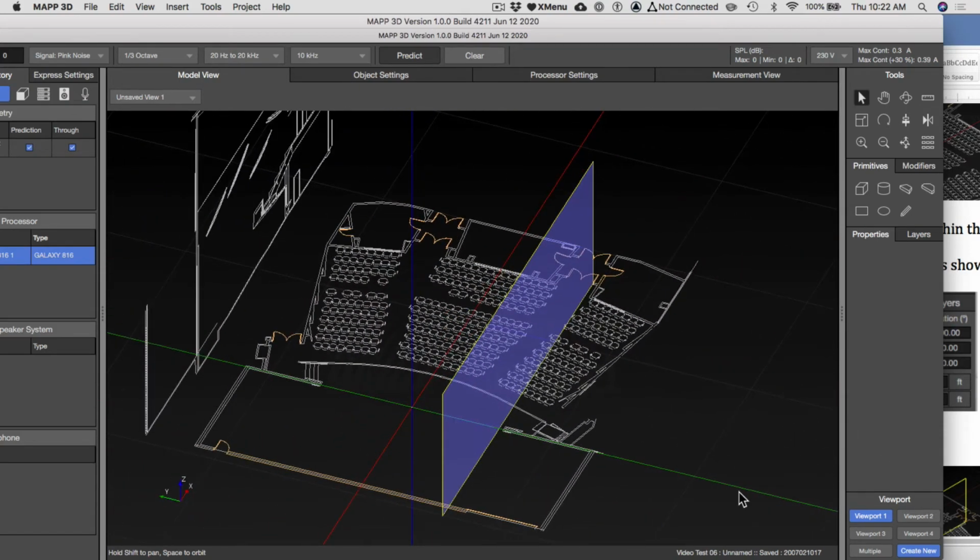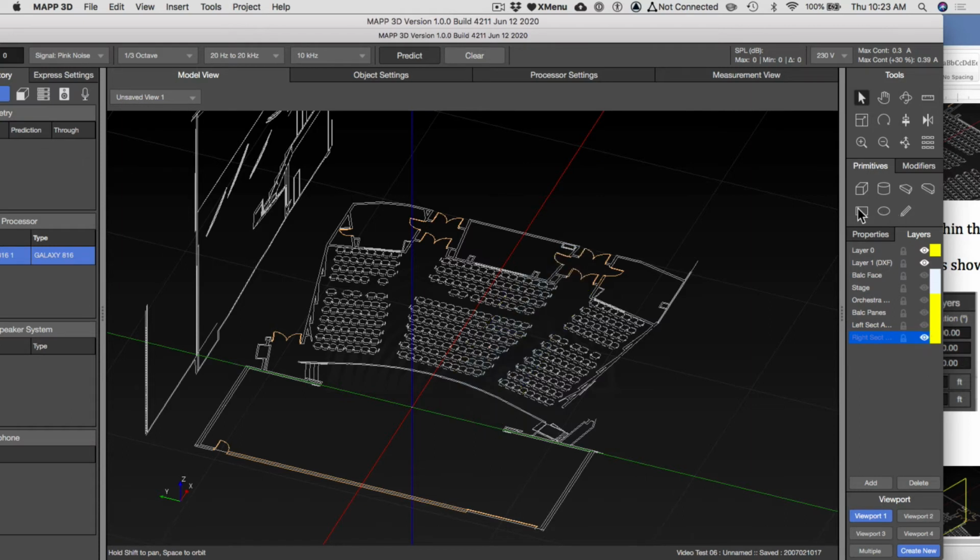So we're going to want to make 3 more of these things. Let's at least get the process started. So let's create the right array, right sect array. And you can hide the previous if you want, so you're not looking at it. Same steps. Take the rectangle primitive, put it in there, select it, and we want to rotate it 90 degrees around the x-axis.